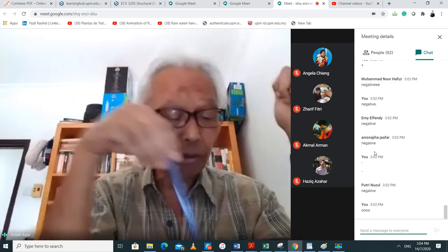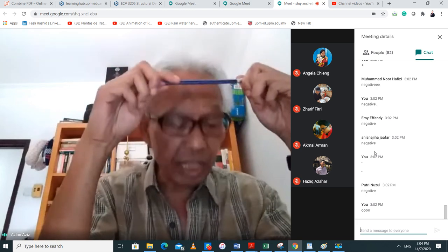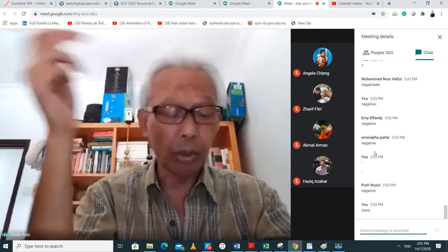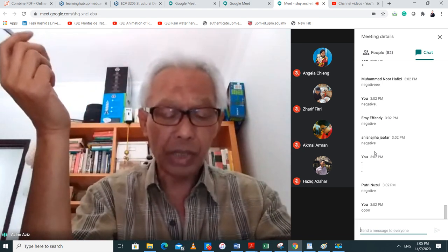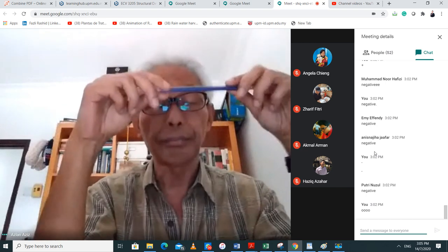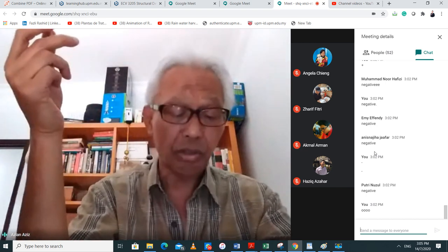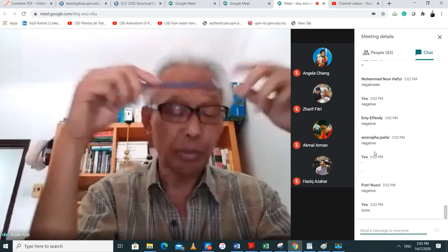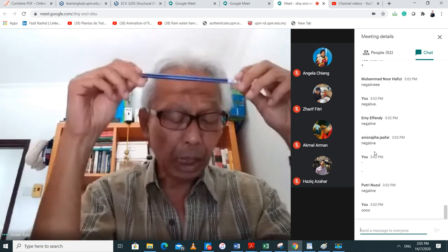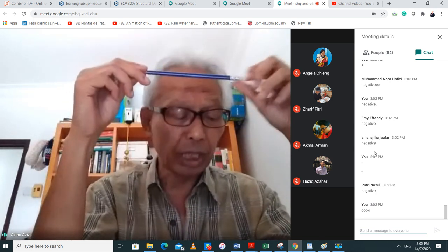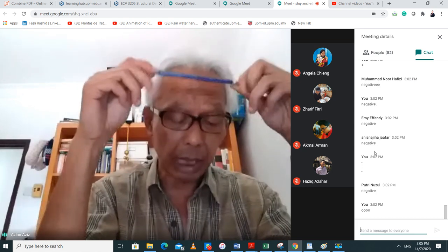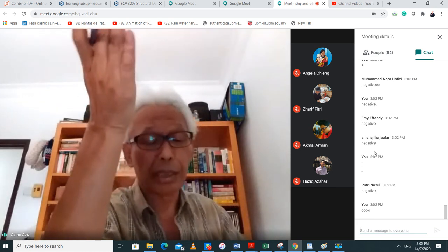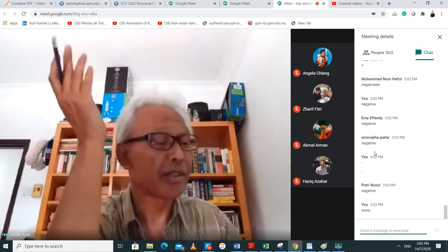You know in which direction is negative. Now you can look at the bottom, and it says that the negative skin friction in end-bearing piles can occur due to consolidation of soft clay layer or silt or peat layer under weight of fill. I have explained to you, you put additional stress on the clay layer, it decides to settle because there is now new dissipation of excess pore water pressure. Or the second part is settlement due to lowering of water table in normally consolidated or slightly overconsolidated clay.